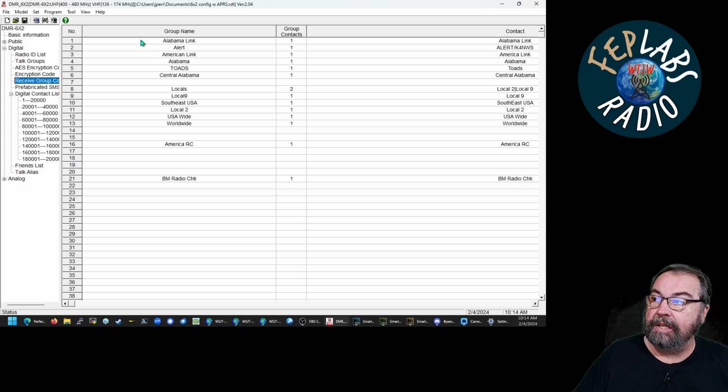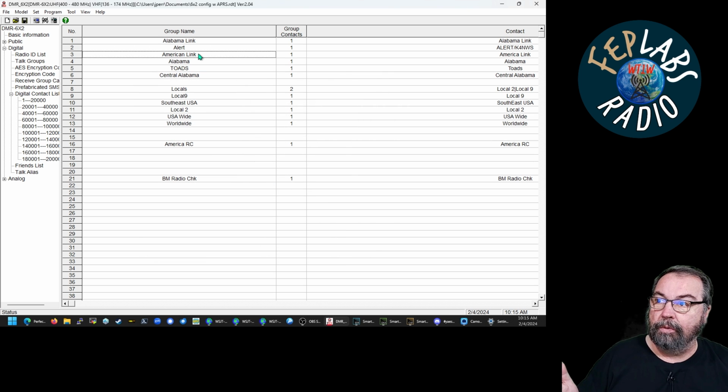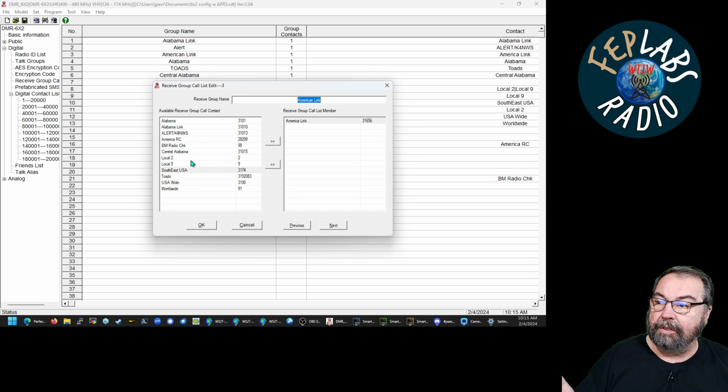And what I've done is I've made a receive group for each specific digital talk group I have listed in step 2. And you can see I made a receive group called Alabama Link, and then I moved the contact Alabama Link into this receive group, and it's the only one in there. Same thing for America Link. I have America Link over here in the group. The group is named America Link, and that's how I've got it set up, so on and so forth for every digital contact I have.